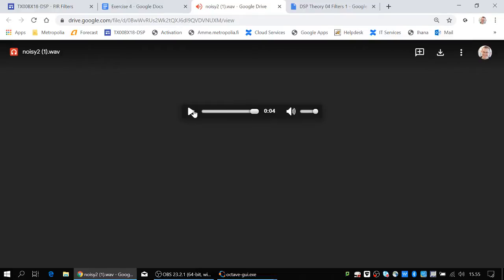And your task there is basically to do the spectral analysis and find out those filter coefficients or filter parameters. Cutoff frequency, stop and start frequency, meaning the transition bandwidth, and the stop band attenuation. So we go back to defining the box.